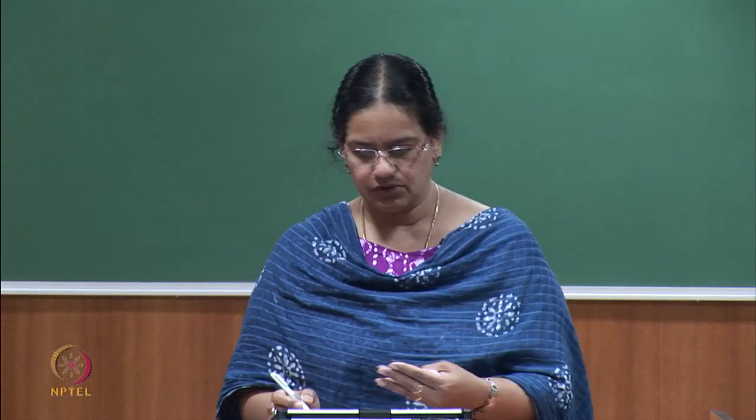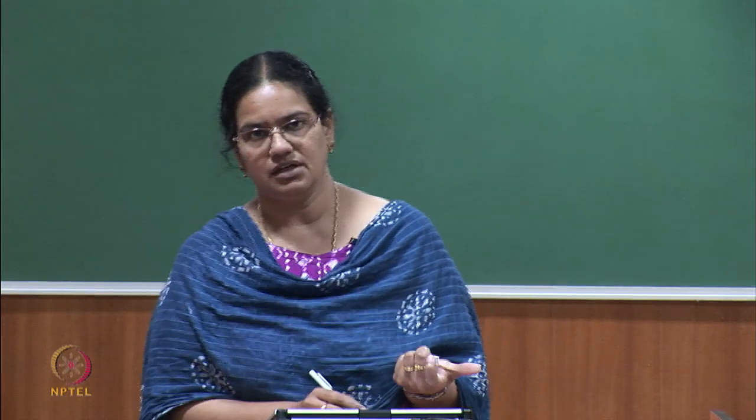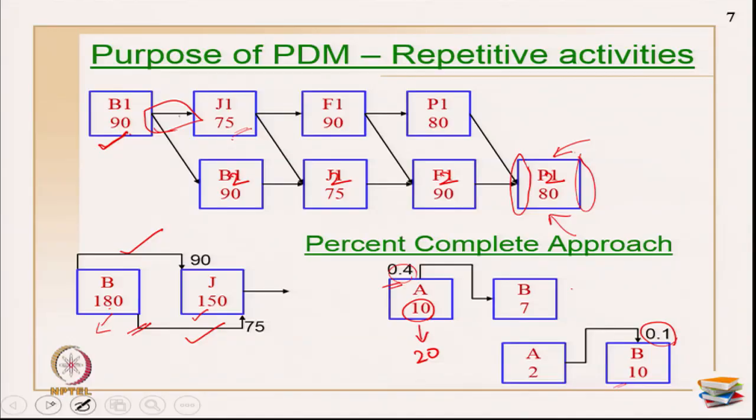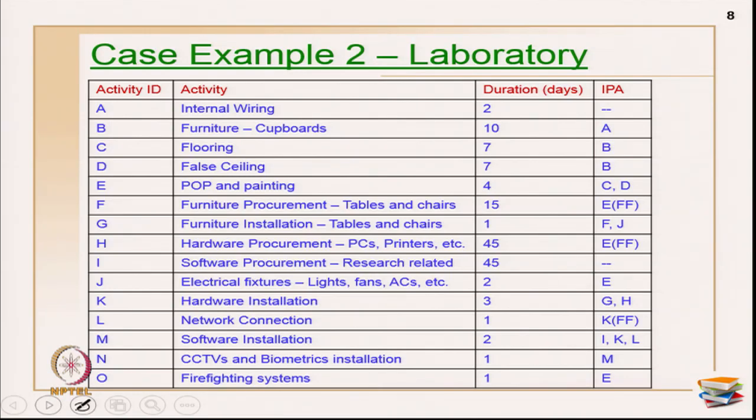Okay. Now, before coming to that, I said there is a prescribed time of waiting and so on. We have very nice examples for all these. For example, in concreting, curing is a very critical task. Instead of showing curing as one activity and then connecting it with the finish start relationship, if you add the duration for curing as a lag, then that shows that it is taken care of, and it is understood by the experts that you have to leave 10 days for curing and so on. So, that is the meaning of all these relationships and the lead lag combinations.